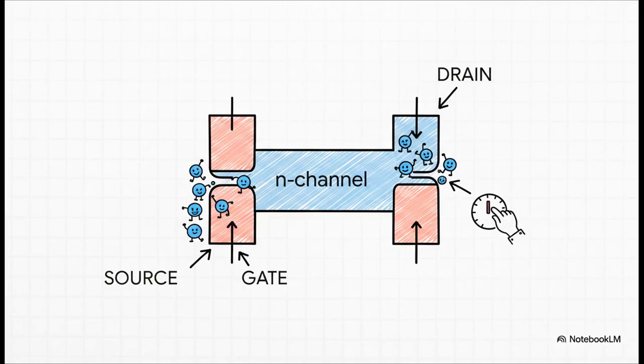Now, every JFET has 3 of those terminals I mentioned, and thankfully, their names make a lot of sense. You have the source, which is where the charge carriers, the electrons or holes, enter the device. They then flow through a little pathway called a channel to the drain, which is where they exit. And then you have the most important part, the gate. This is the control knob. The voltage you put on the gate is what opens or closes the flow of traffic.